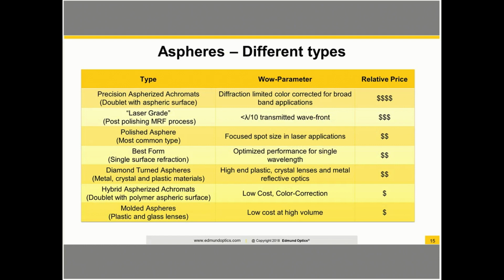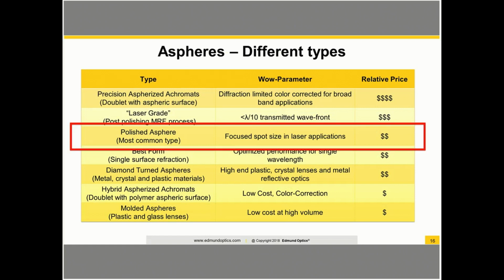Oh, thank you, Lars, for asking this question, because this is a very good question. There are a few parameters, or aspects, that need to be taken into account while selecting the type of Asphere to be used in the system design. One is whether the system is going to operate over a wavelength range, or is this going to be a single wavelength application. Another one is optical power. The third one, of course, is the cost budget, which is normally a very strong constraint. And last but not least is the actual optical performance requirement. And I would say that as a rule of thumb, a good starting point would be to try to use power Aspheres.